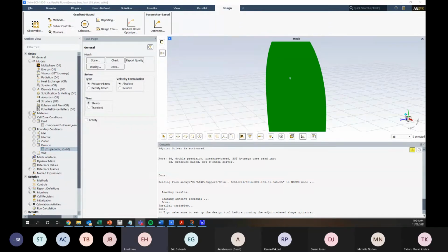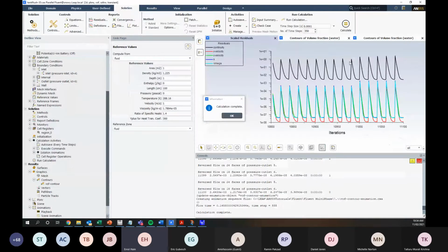Angus, for a transient simulation, for which residuals converge within time steps, should the lowest residual for each subsequent time step decrease? No, it shouldn't. Actually, they should remain fairly constant. So it should look like this, but only say 1 or 2 iterations per time step, and we want that time step to be going below 1e-3. As long as the bottom one goes to 1e-3, then it's all converged. And it should stay a constant line along.